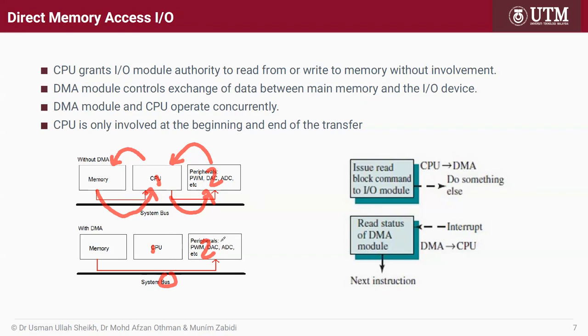So in the STM32, they don't use a single bus, but a cross bus switch, which is even better, because on the cross bus switch you can perform parallel transfers. So the STM32 that we have is actually more advanced than what we see here. And the DMA is more efficient because there's no waiting.